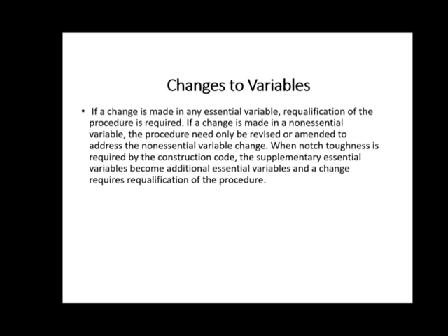This would be something like changing the base metal. Let's say I have a P number. Say I have a welding procedure that I'm qualified to weld stainless steel to stainless steel, P8 to P8, but I want to change it so I can weld P8 to P1, which would be stainless steel to carbon steel. Well, then I would have to requalify my procedure.